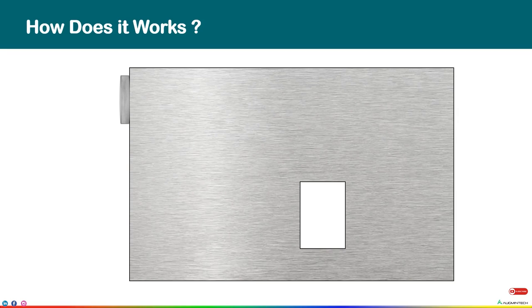For UT of a test piece, not a very large transmitter is used in most cases, but rather a compact one which generates a short ultrasonic pulse. You can see in this diagram that at a place free from defect, the UT pulse travels to the right end, which is also known as the back wall. The pulse is reflected and recorded again as an echo.